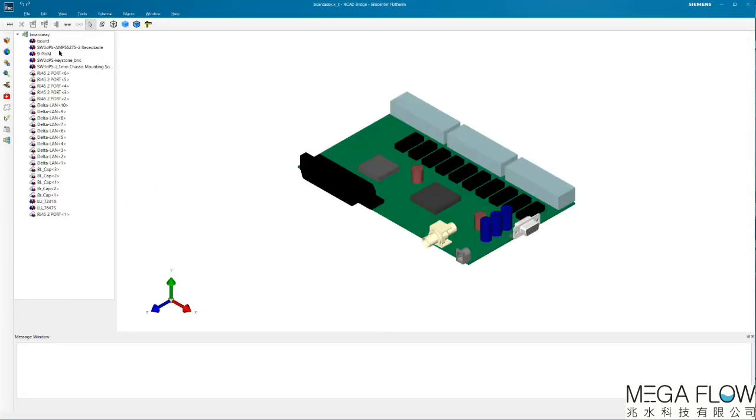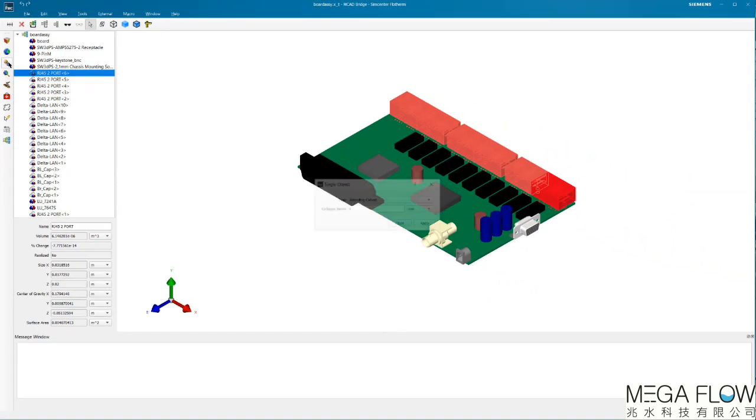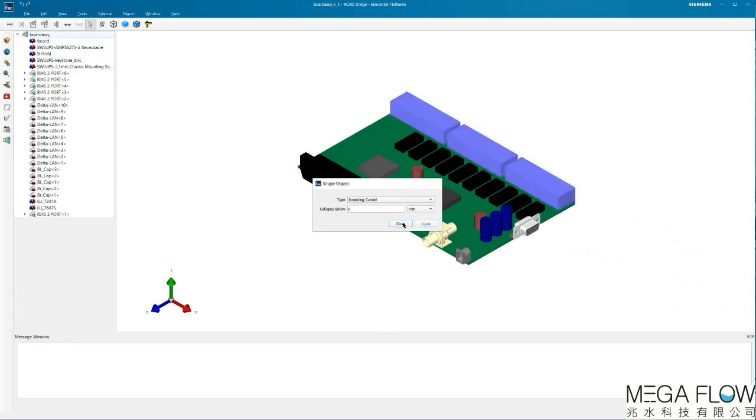Once you have imported your CAD model, the first changes you see are in handling instances. These are multiple linked CAD bodies represented with the icon of a link with a cog. Each instance name is appended with the number of the instance. If you act on one instance that is linked, you will act on all. So you can replace one here with a single cuboid, and all of them are replaced with a single cuboid.